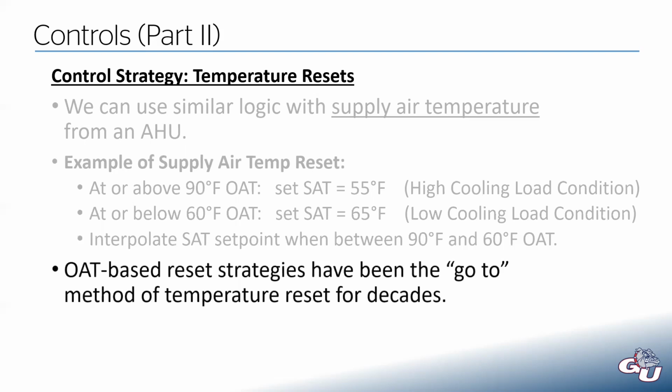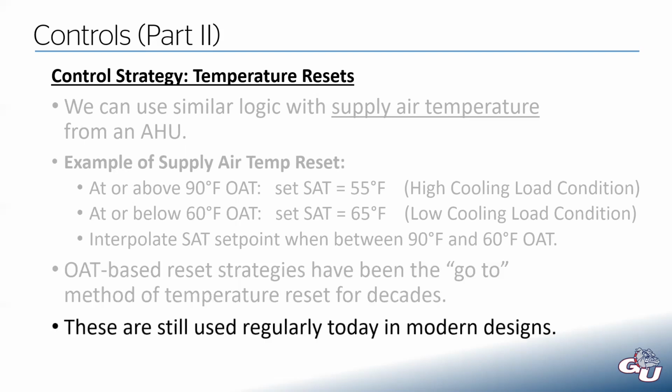So these are called outside air temperature based reset strategies. And these have been used for decades. They're still used today. The energy code still says this is an acceptable way to reset your hot water or chilled water or supply air temperature.